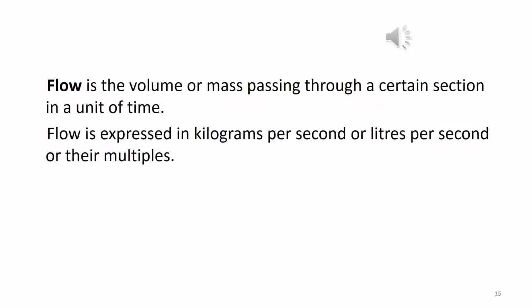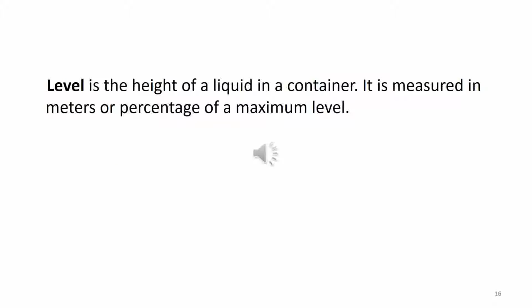Flow or flow rate is the volume or mass passing through a certain section in a unit of time. Flow is expressed in kilograms per second or liters per second or their multiples. Level is the height of a liquid in a container. It is measured in meters or percentage of a maximum level.